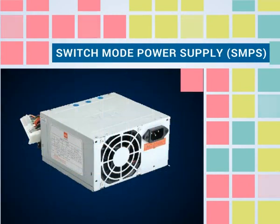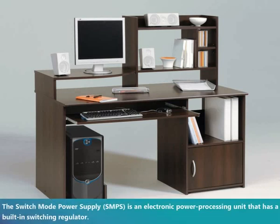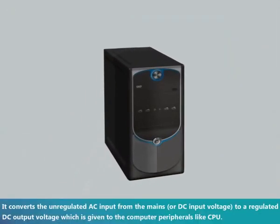Switch mode power supply, SMPS. Let us see about the switch mode power supply. The switch mode power supply is used in computers. The switch mode power supply, SMPS, is an electronic power processing unit that has a built-in switching regulator. It converts the unregulated AC input from the mains or DC input voltage to a regulated DC output voltage, which is given to the computer peripherals like CPU.